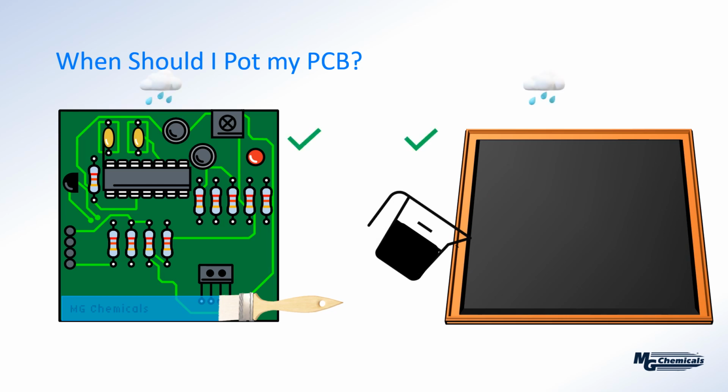Well, an obvious choice here is that for environmental stresses, both solutions are appropriate. Okay, and you can argue that potting and encapsulation provides enhanced protection against environmental stresses, and that more or less is true, but often people will opt to conformally coat either for ease of use or for weight considerations. And again, there is advantage to potting, but it's not that significant that it would sway you away from conformally coating. So that is a situation in which the two solutions more or less line up, and there's no clear advantage one versus the other.